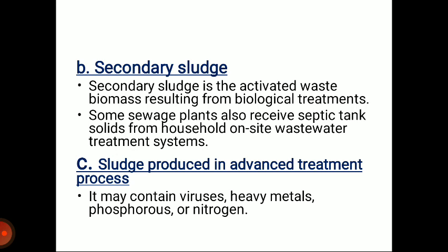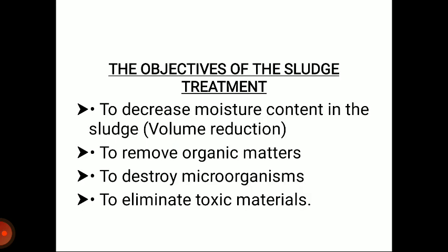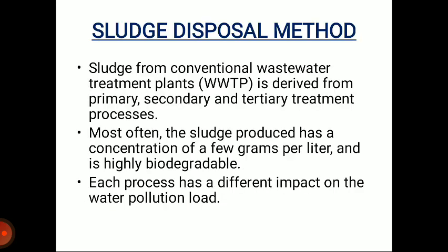Third point, sludge produced in advanced treatment process. It may contain viruses, heavy metals, phosphorus or nitrogen. The objectives of the sludge treatment are to decrease moisture content in the sludge, volume reduction, to remove organic matter, to destroy microorganisms, and to eliminate toxic material.